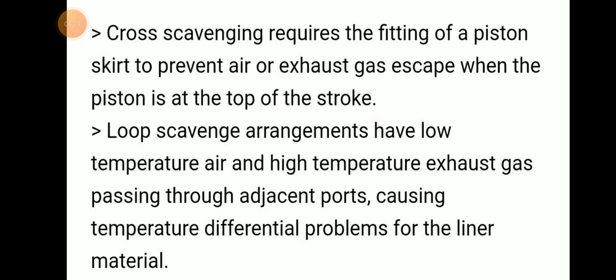Cross scavenging requires the fitting of a piston skirt to prevent the exhaust gas escaping when the piston is at top of stroke.